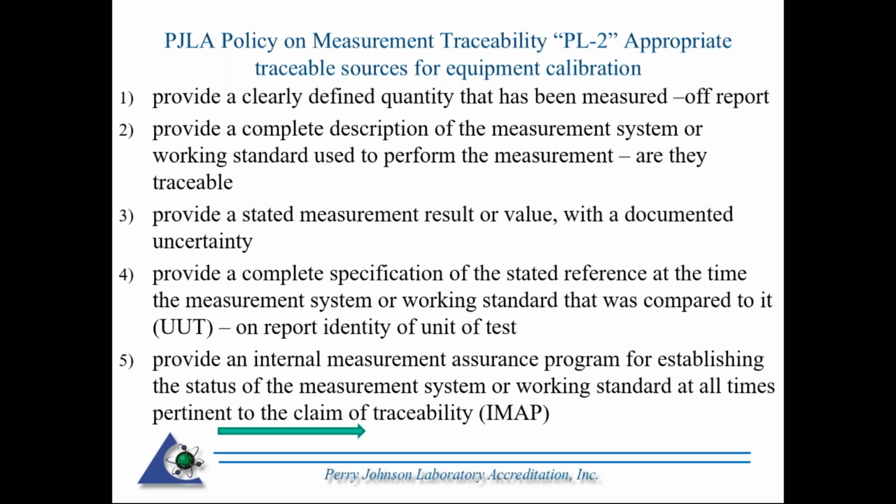Provide a complete description of the stated references at the time of the measurements, or the working standard to which it was compared. In other words, your unit under test, what you are sending off, has to be provided on the report. Perhaps it's a caliper or a micrometer, sticking to that example. That needs to be identified on the report, and ideally a unique identifier such as an ID number or a serial number should accompany it.